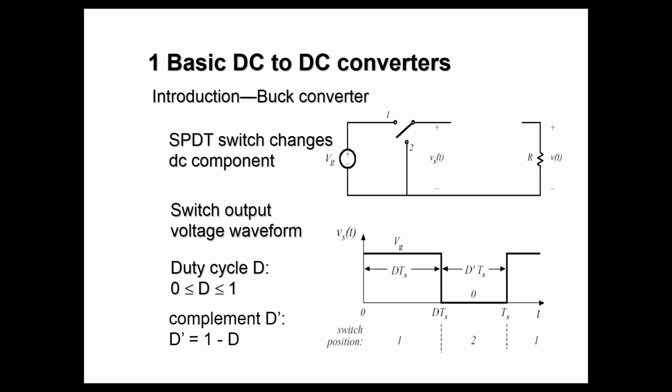So in that case, when the switch was at position 1, the load was getting a voltage of 100 volts, and when the switch was connected at position 2, the load was getting a voltage of 0 volts. So later on, when we derived its average voltage and set the value of D equal to 0.5, the load actually turned on, and in that case the efficiency was also improved.